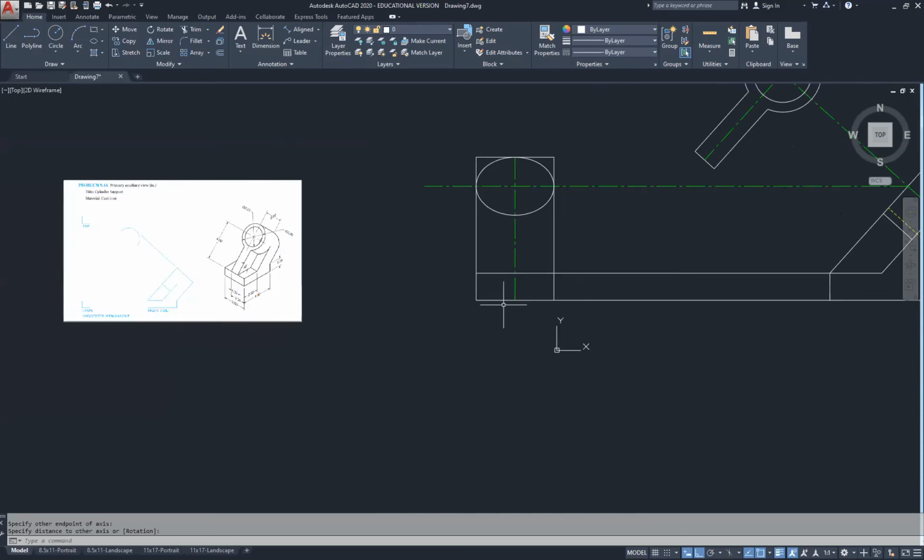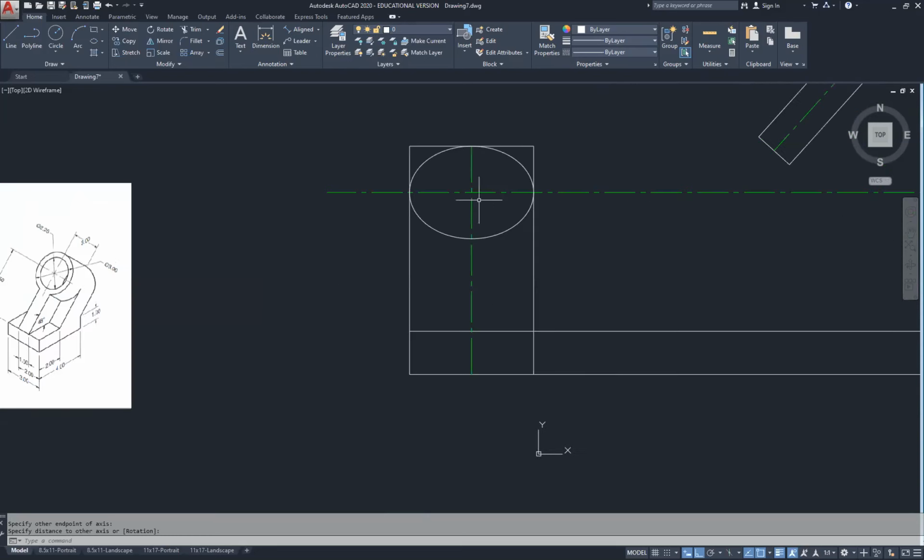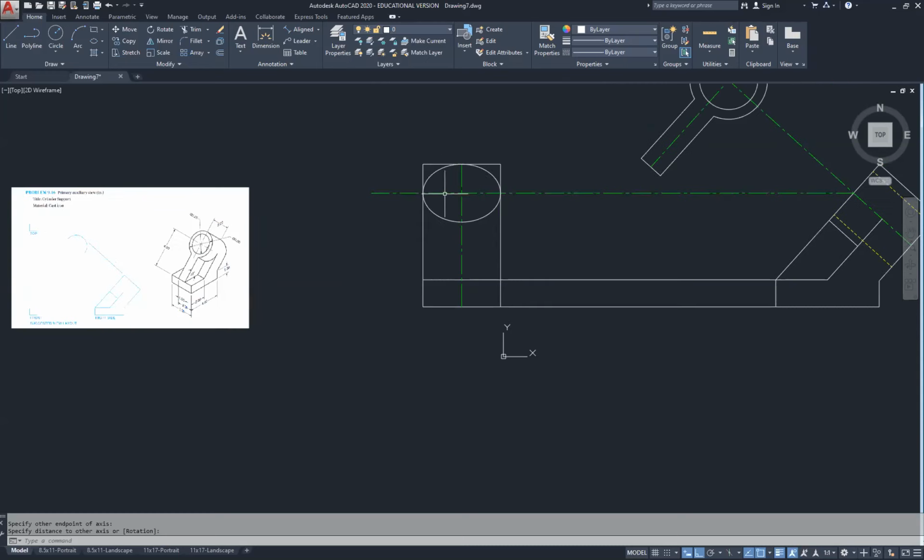If you take a coin and you rotate it in your hand, holding the left and right side of it and spinning it around, you'll notice that face just gets shorter until it becomes down to nothing. And then it spins back around, it becomes a circle again. So that is the ellipse that we need to represent for the very top surface here.